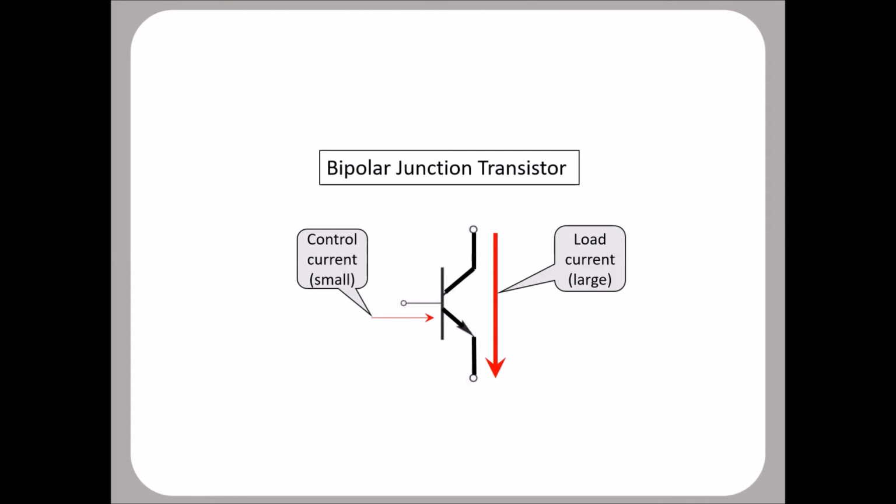And in power operation, almost every transistor now operates either turned fully on, by which we mean it has virtually no resistance between its two main terminals, so that's between this terminal here and this one there, and that depends on the current fed in to this terminal. So we can switch it from on to off, make it look like a switch that's on or off. So instead of those mechanical switches, substitute transistors.